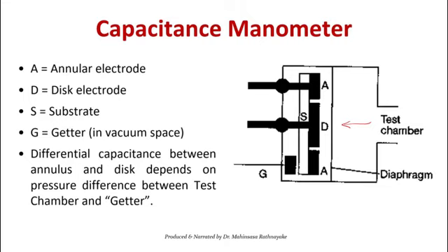Based on that, you can scale the thing and measure, or otherwise you can use that voltage output for a certain electric circuit or electronic circuit to control or for digital measurement. So this is really important because in another lecture I will discuss in detail about strain gauges. They extend the discussion into load cells also. Load cells are also very important when we talk about mass measurement or weight measurements in the industry. So when we discuss load cells, we will discuss strain gauges a lot, because strain gauges are important in modern transducers.